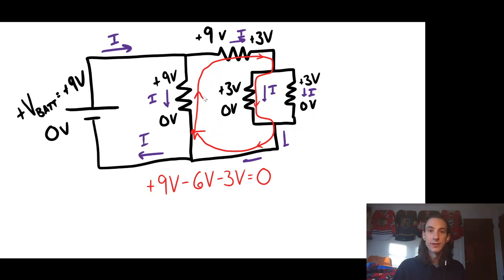In this case, we'd be working against it, so we'd be adding energy, because what the resistor does is take energy away. If we reverse that process, instead of taking energy away, we're going back to the state where we had energy. So we're adding energy in here. If we look at this case, we start at 0, then we add 9, so we have plus 9 volts. And then same thing here, minus 6, minus 3. Within that loop, we've ended up at 0.